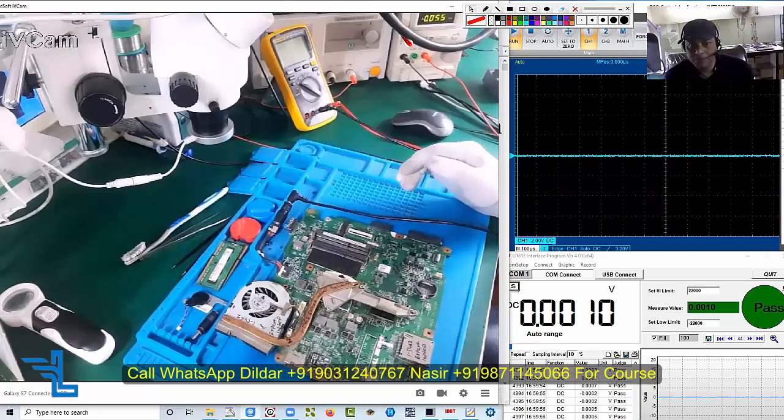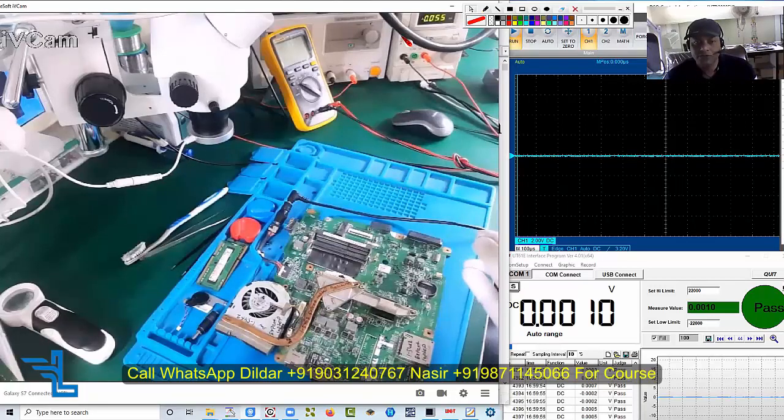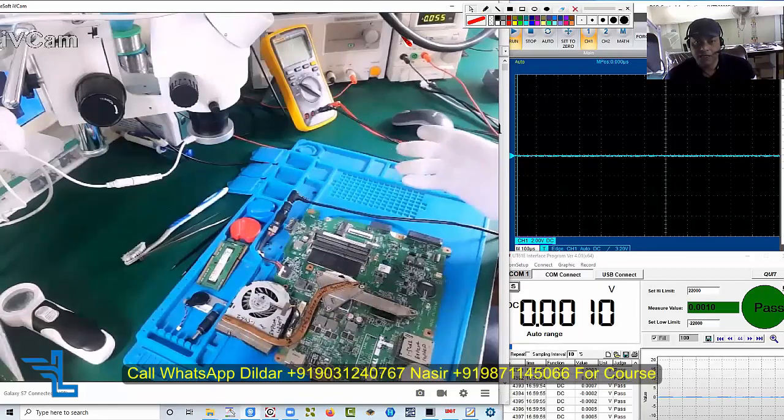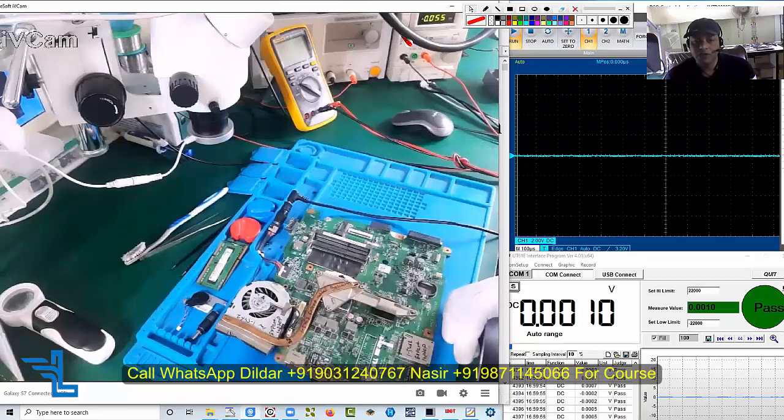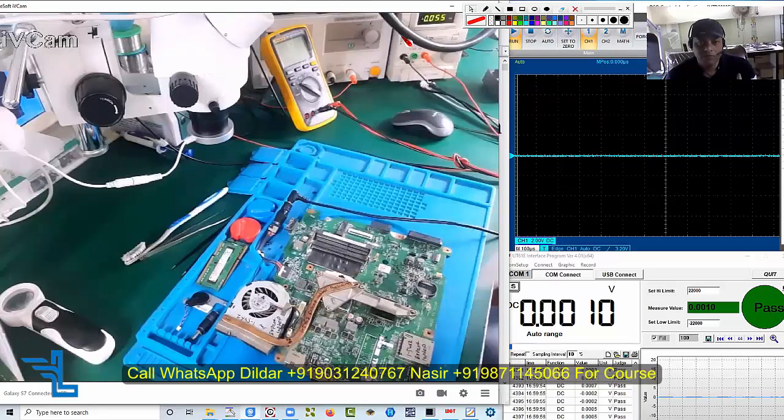I think this is a first generation motherboard, but I would like to shed light on this issue: generation doesn't matter with your technology, like the generation of 19 volt, the generation of 3.3 volt and 5 volt, RAM regulation, and your core voltage, VCCP and VCCSA voltage. These voltages and concepts are almost the same from Core 2 Duo till the latest generation. So let's go into that matter of what generation it is, but the concepts are almost the same in every architecture.